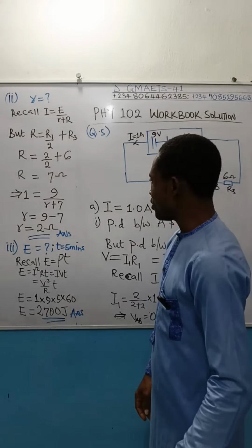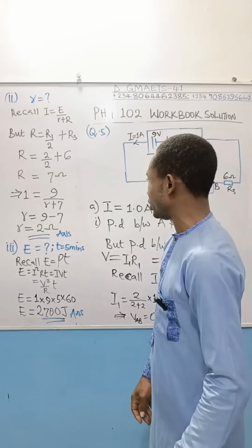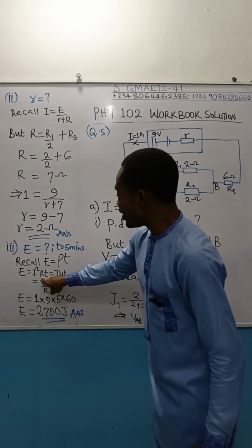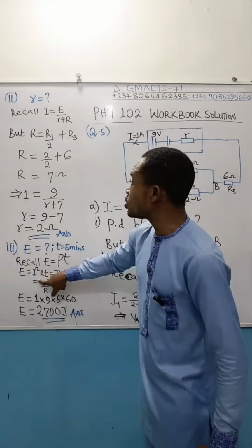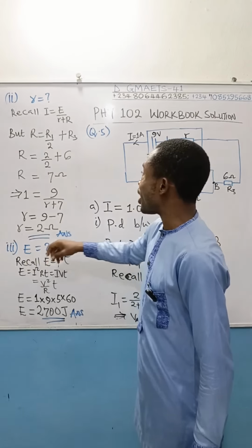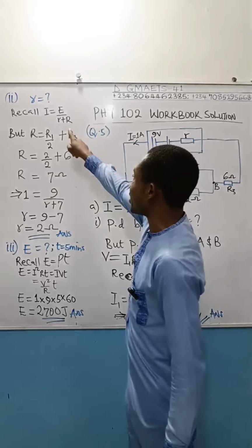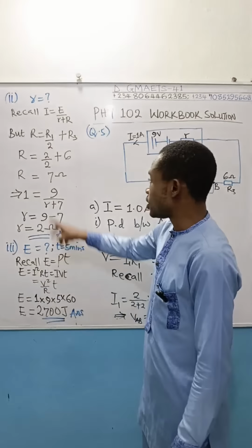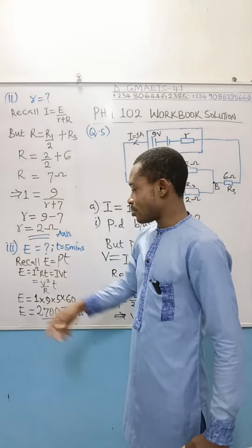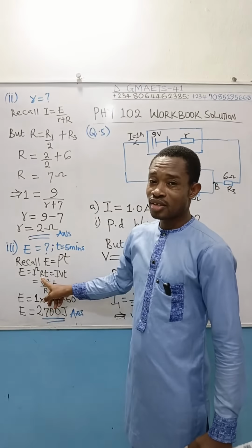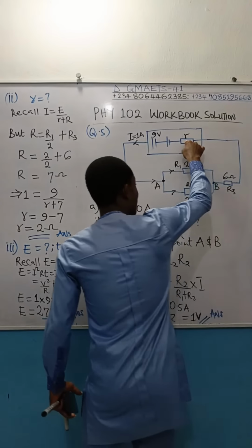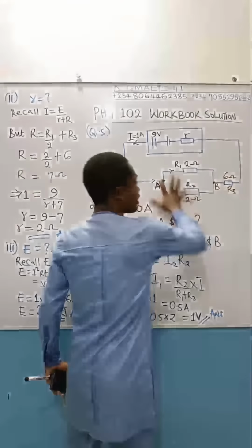Okay, the R there is meant to be 9. Because the resistance you are going to use here, please take note, will be equal to the overall resistance in the circuit. Look at it, this plus this. So you are not using this 7 directly. I'm sorry that the formula came in this format. In this circuit, there are 2 resistors: the internal resistor and this external resistor.